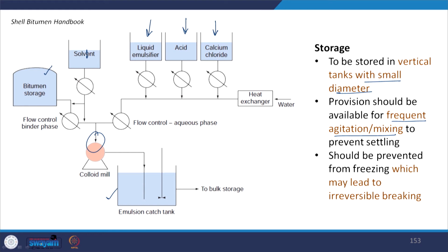Also, the emulsion is susceptible to frost action. So, it is important that it is prevented from freezing, otherwise this may lead to irreversible breaking of the emulsion and the same homogeneity cannot be restored.